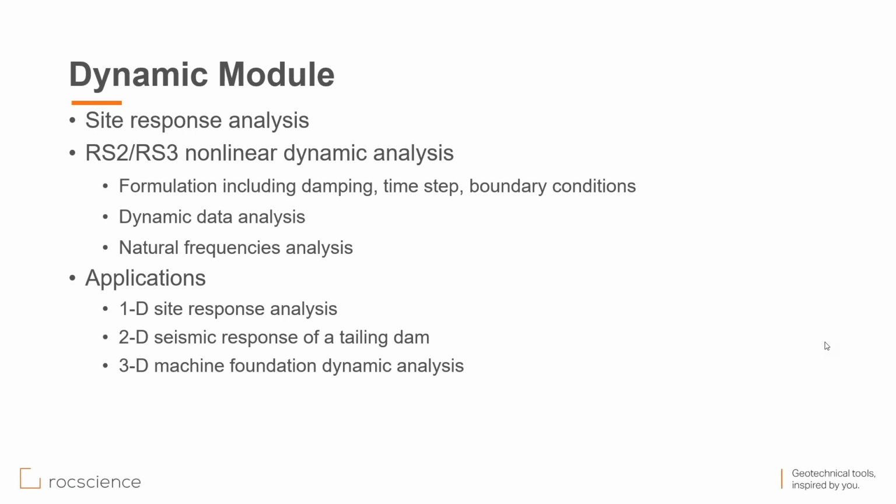And then we run another pass and get another value of the peak shear strain and the peak shear stress. The process keeps iterating until the difference in the shear stiffness is smaller than a tolerance, and that is when we accept the solution.